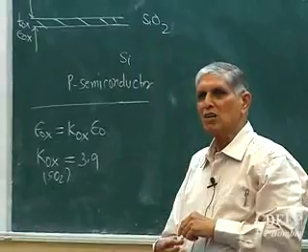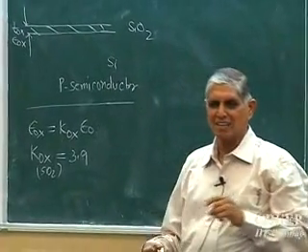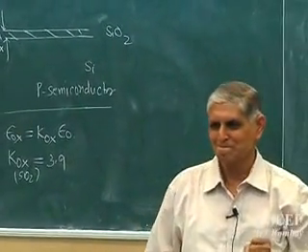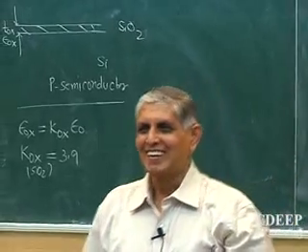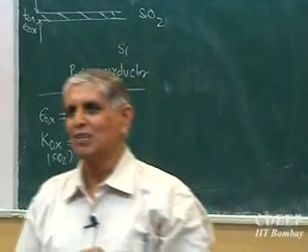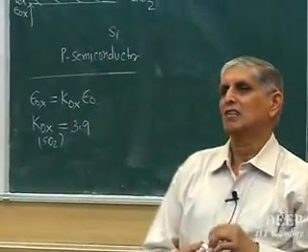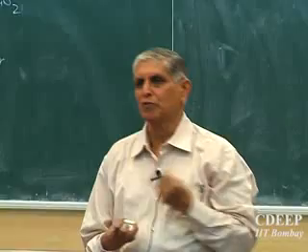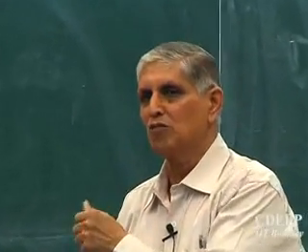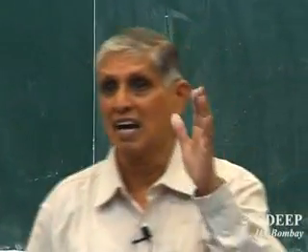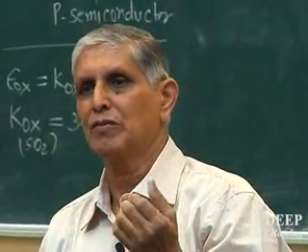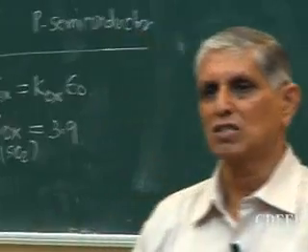Do you know the dielectric constant is related to the refractive index? So the dielectric constant of a material is in some way proportional to the refractive index. Glass has a refractive index of 1.45, and that has some relation with this 3.9. SiO2 is a glass. So glass has a refractive index of 1.45, whereas the dielectric constant is 3.9.